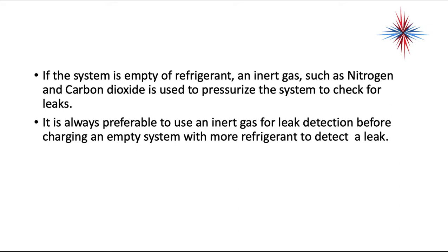Now, why an inert gas? An inert gas will not change pressure based on temperature. Once you put 170 psi into that system, as long as there's no leak, it's going to remain 170 psi regardless of what the temperature does. Inert gases do not have a temperature pressure relationship, or a very minor one.